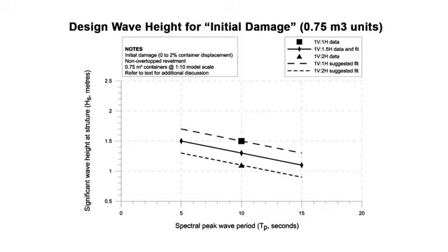This was similar to the last example, but we change the slope to 1 in 2, so a flatter slope. Interestingly, if you're used to designing rock structures, you'll think that with 1 in 2 the structure will be more stable. It goes converse to that with geotextile structures. Our threshold wave height at the structure is actually lower for a 1 in 2 slope. At first we were a bit perplexed by that, but there is an explanation which I'll get to.